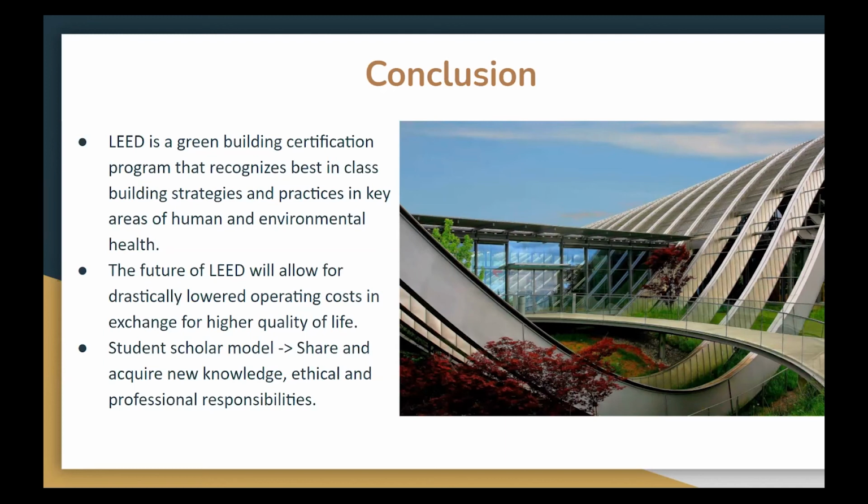There's one more question from the audience. What is the largest size moment frame components, both columns and beam, you used? And is this an ordinary moment frame? So this is actually not an ordinary moment frame. It is shown in the California standards that ordinary moment frames are prohibited. So we will use special moment frames for our building design.